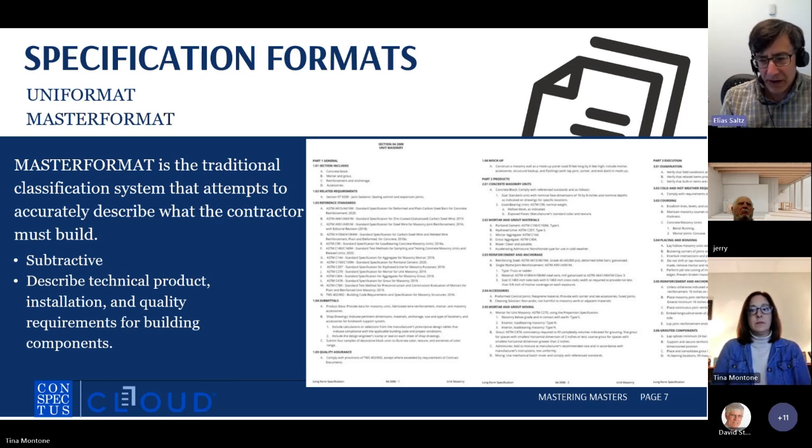Right, and then MasterFormat. Everybody in here who's a specifier who deals with construction specifications knows MasterFormat. It's the numbering and titling system published by CSI, and it's the way that we organize our full 3-part construction specifications. So for 3-part construction specifications organized by MasterFormat, typically you start working from some sort of master,